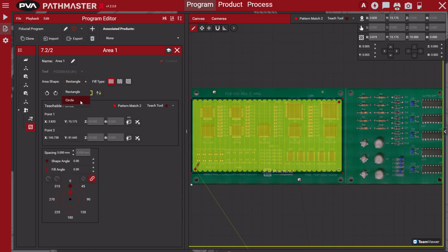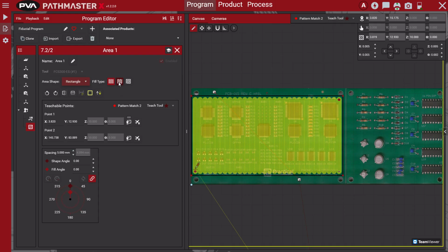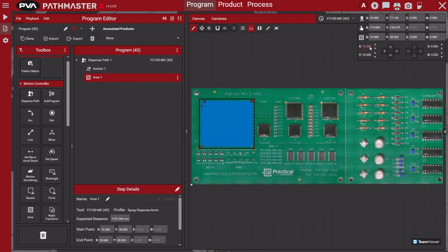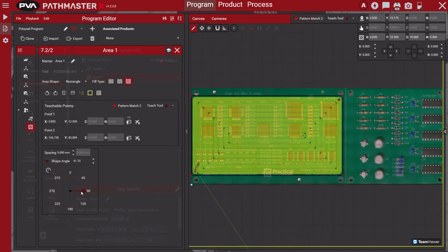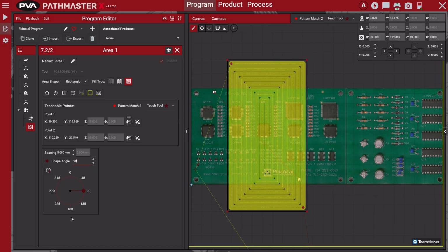Within PathMaster X, users have access to many advanced options to edit their program steps, including creating offsets, rotations, arrays, mirrored paths, on wait, and off wait. Creating an offset for a program step allows the user to move a selection by a specified coordinate amount. The rotation option allows paths to be rotated by any angle specified by the user.